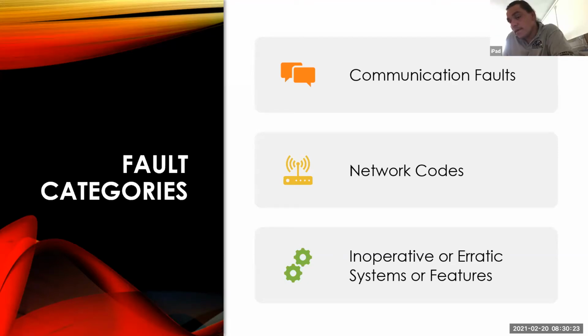So you just slide a heat shrink on it and then just melt it? Yep. And the good heat shrink has a glue on the inside that you'll see ooze out each end. That thing is glued solid in there. They've also got the solder heat shrink. Have you seen those? Yes. It's a heat shrink with solder inside, and as you're heating it up, it actually melts and that's nice. Solders your connection. Yeah, I've seen that too.